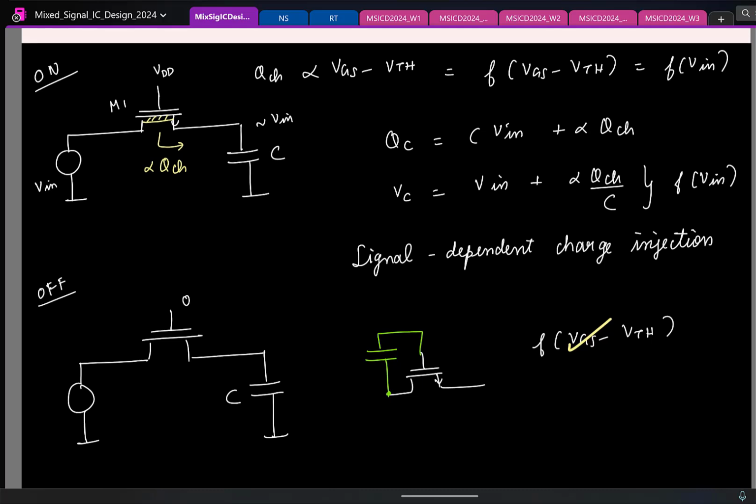But unfortunately the story doesn't end there, because it turns out the MOSFET also has one more terminal, which is the body, substrate or bulk, whatever you call it. And in most CMOS processes you don't have provision to connect the body terminal of the NMOS to any arbitrary potential you want, because it is shared by all transistors.